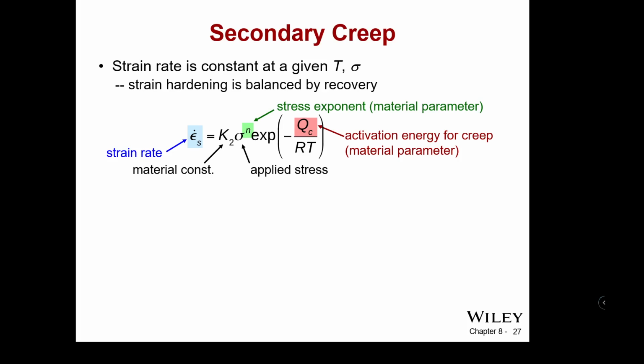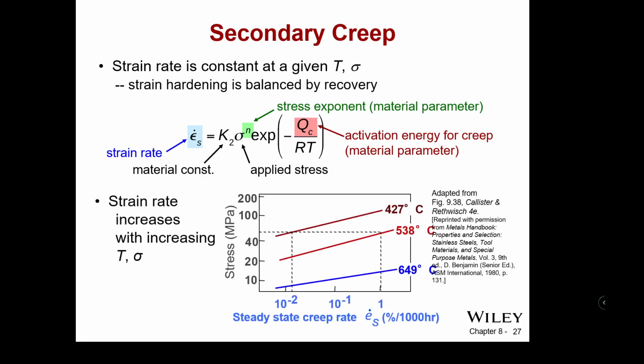So that has to do with the kinetic energy and how much energy is going to creep. That ratio is an exponential factor, but it's a negative. So it's a reducing exponential, because the more activation energy needed, the less of a temperature dependent effect you're going to have on that strain rate. So that should make sense rationally.